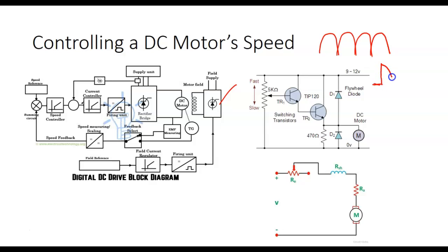We called it firing, and so we'd end up with something like that. Now you wouldn't see it, because across a DC motor, when you cut it off, the DC motor acts like a generator. So if you looked at this with an oscilloscope, it almost looked like DC. But what would happen is the average DC would go down and the motor would slow down.